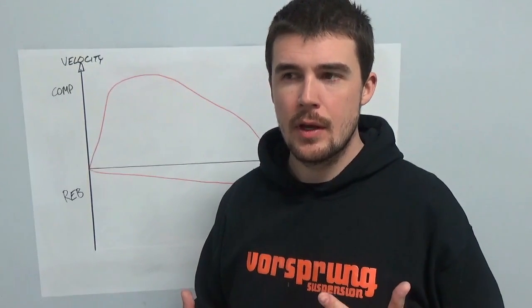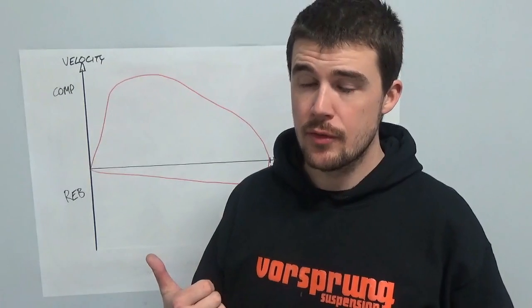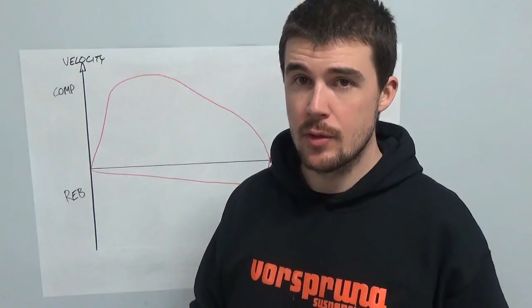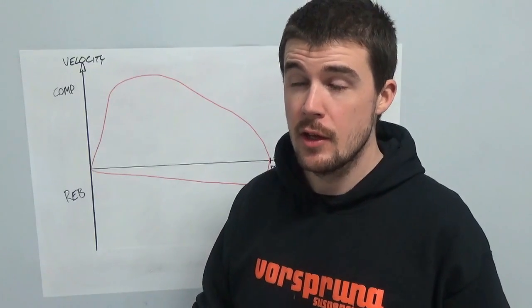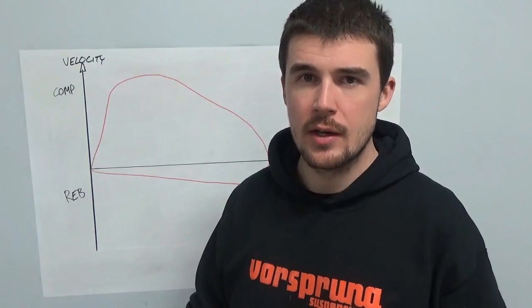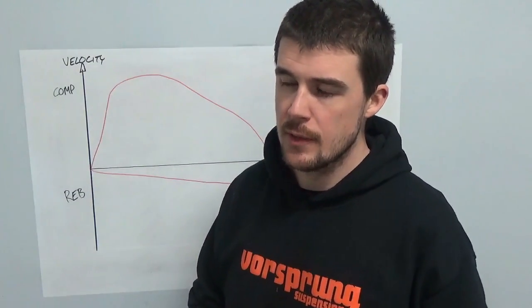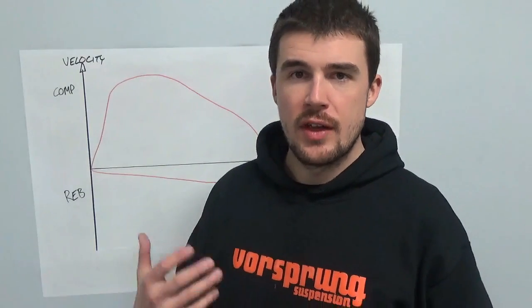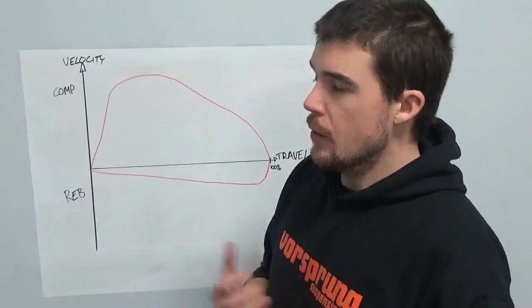So ramp up, how? Is it a more progressive damper curve in terms of generating disproportionately higher forces at higher speeds? Typically not, because that will give you something that becomes quite harsh and very unsupportive initially. Or is it something that ramps up towards the end of the stroke, as we've seen explicitly advertised by a current product? Obviously that isn't possible.